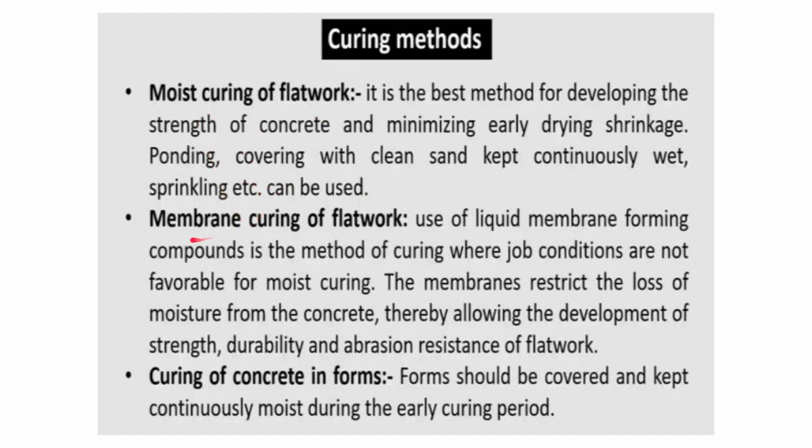These are the ways we can keep the flatwork moist. That is the moist curing, directly applying water, the wet curing. So how can we go to membrane curing? Let us see that. We can use liquid membrane forming compounds. These are the methods of curing where job conditions are not favorable for moist curing.